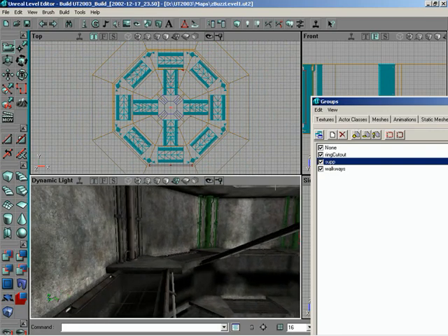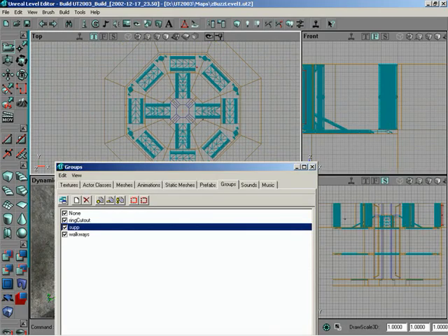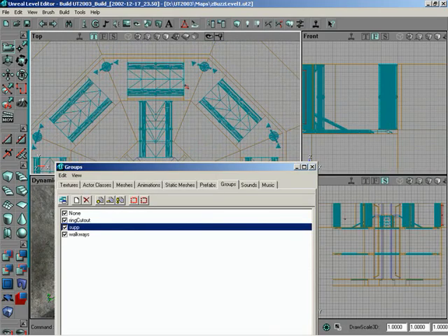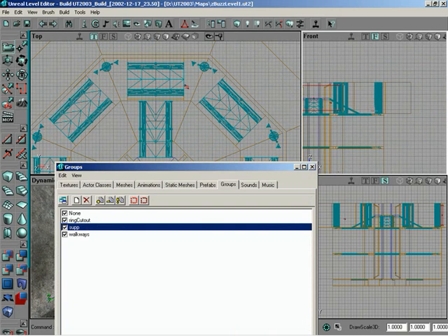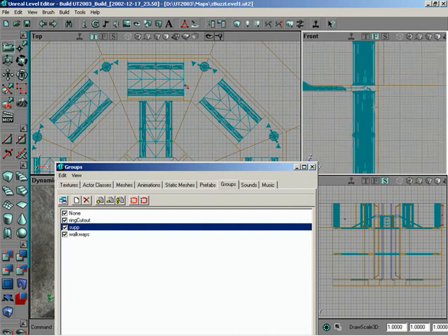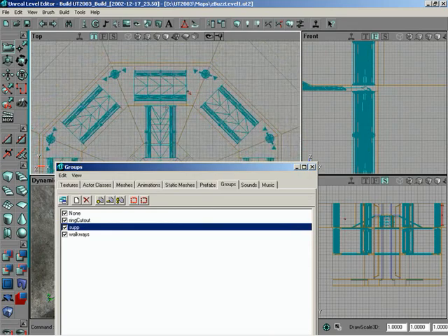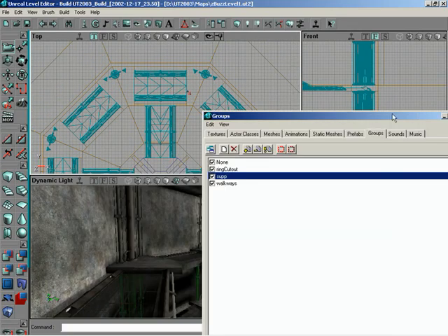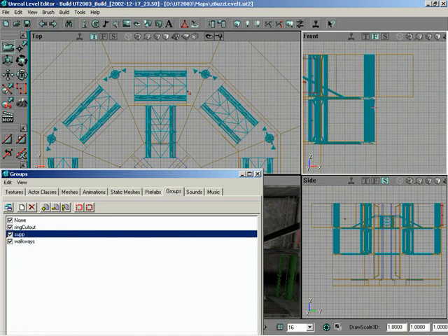And there we have, at least for the top, 8 supports all the way around. Now we can just easily copy that whole group and take it down 2 more times. Select all one last time, and let me duplicate that off. Then center it up, and then I can move it down to the next level. Zoom in a little, make sure I have this centered up. Still centered there, good. I still have just those 8, so let me duplicate those one last time.